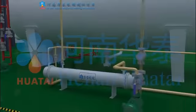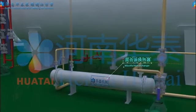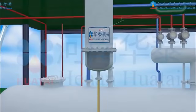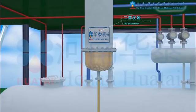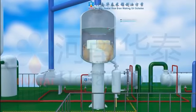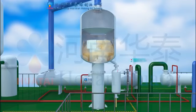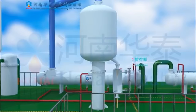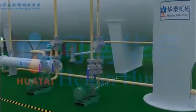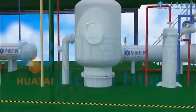The number 1 evaporator extraction pump sends the mixed oil to the heat exchanger. After that, the oil is sent to the number 2 evaporator, which is heated by indirect steam. The mixed oil presents a rising film state when it goes through the stainless steel tubes. The solvent gas is separated by the vapor-liquid separator on the top of the number 2 evaporator. After the second concentration, the mixed oil goes into the temporary storage tank, and is then pumped to the steam stripping tower by the number 2 evaporator extraction pump.